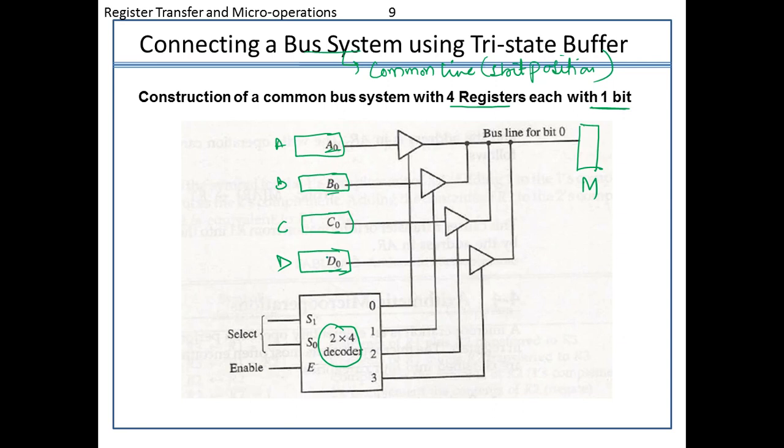The reason being that I have the number of registers equal to 4. How will this help me? These are the two input lines. We know how decoders work: for 0 0, D0 will be active; for 0 1, D1 will be active; for 1 0, the second value will be active; for 1 1, the third value will be active, right? There is also one enable, which just acts as whether the circuit is connected or not.